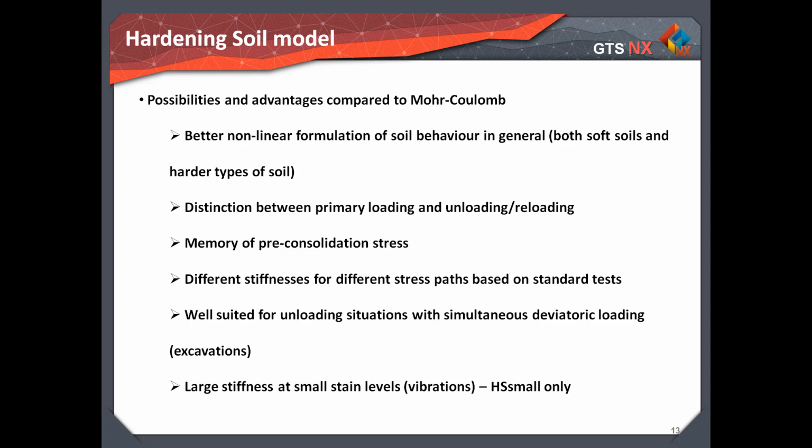Possibilities and advantages compared to the Mohr-Coulomb model are better nonlinear formulation of soil behavior in general, both soft soils and harder types of soils. Distinction between primary loading and unloading-reloading. Memory of pre-consolidation stress, and different stiffness for different stress paths based on standard tests.